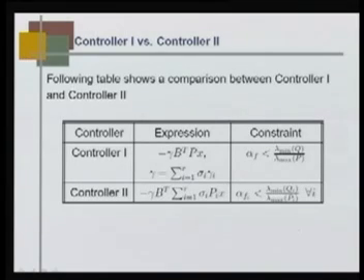Okay. So, this is our controller 1, where the structure is minus gamma B transpose P x, where gamma is given by this, and this gamma makes the controller time varying; the gain is time varying. X is my state. So, minus gamma B transpose P is a time variable quantity, not a constant, because gamma is varying.